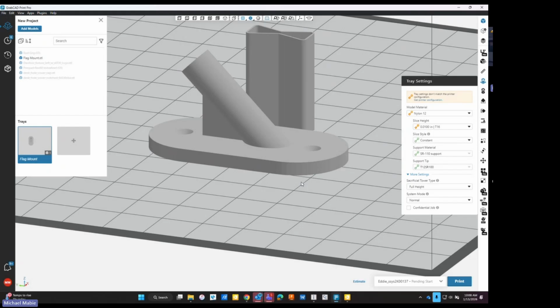Between 200 thousandths and a ½ inch, I would recommend going with normal. And anything a ½ inch thick or greater, you're going to want to run brick mode, again, because we're actually changing the envelope temperature. Now, when in doubt, I would probably say stick with normal, which is obviously why it defaults to normal.